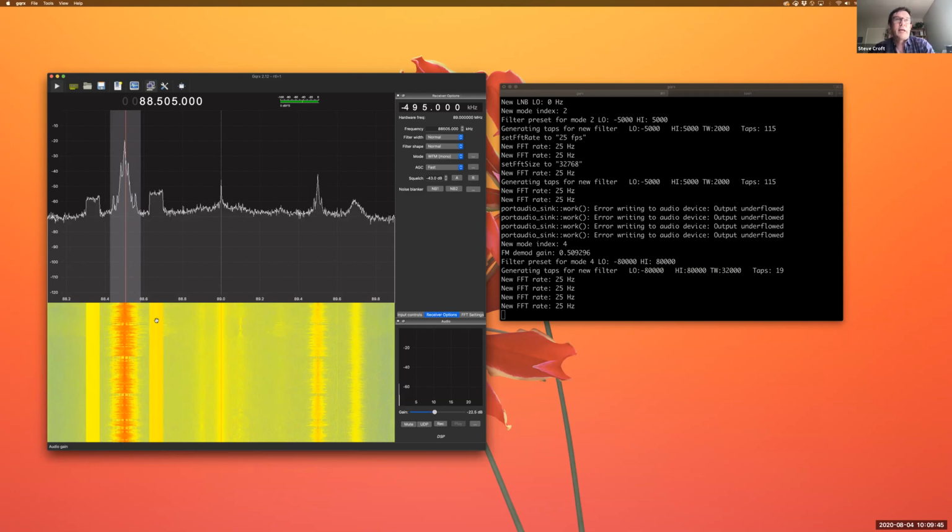And so there's a couple of key things that you can see here. One, instantaneously, you have the spectrum at the top, which is just over some small interval in time. Basically, the power that's coming in is a function of frequency. Scrolling down here, the waterfall plots are the same data, and you can see why we refer to these as waterfall plots, because it looks like water coming over a waterfall, where the water that came over most recently is up at the top, and then it's flowing down towards the bottom here. And this is the FM signal.